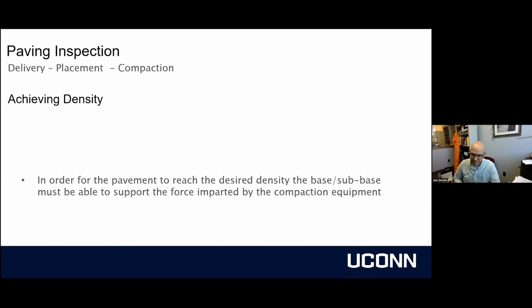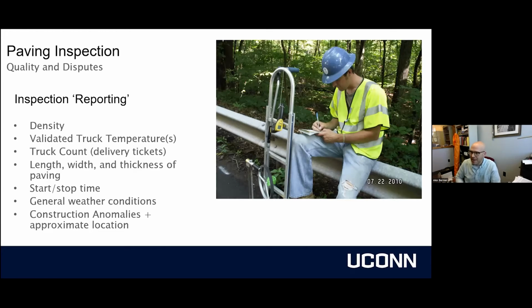You'll experience this if you've ever paved on a full depth construction where you're paving on aggregate. It's usually very hard to achieve density for that first lift. Once there's asphalt down that's much stiffer, it's much easier for the rollers to beat against that. And that makes sense, right? If you try to knead a piece of dough or Play-Doh on a pillow, it's not going to work, versus putting it on a counter and pushing down on a countertop. That's the concept we're talking about here.